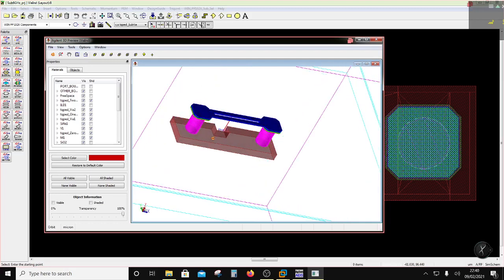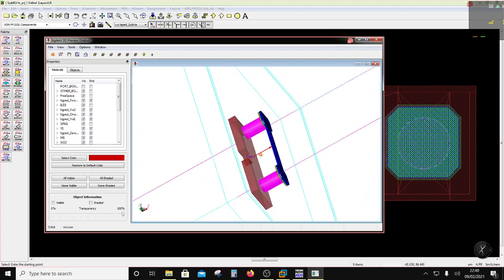So what you have to do is, first of all, find out what the inductance is. So you have to EM simulate this. Now you should EM simulate with a DC point in it, because all the current will go through this. So your simulation will be from DC to the frequency where you are designing, almost the fourth harmonic of it. So for example, let's say I'm designing at 5.8 to 7.2. So 7.2 times 3, at least third harmonic or fourth harmonic should be there, right? So if I am doing 7.2, 40 gigahertz is a frequency up to which I will characterize this.